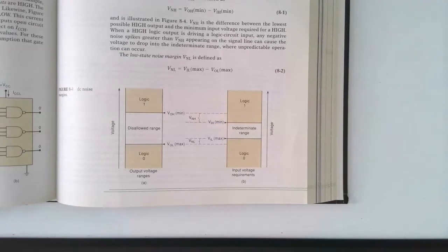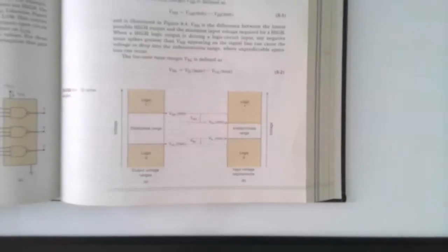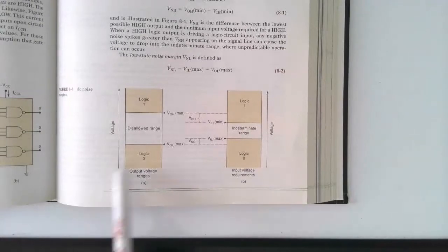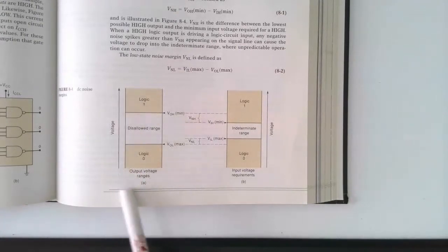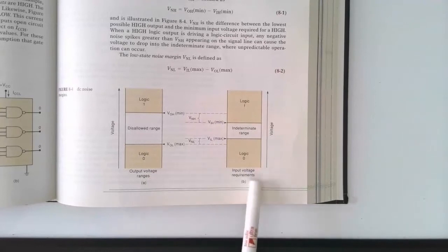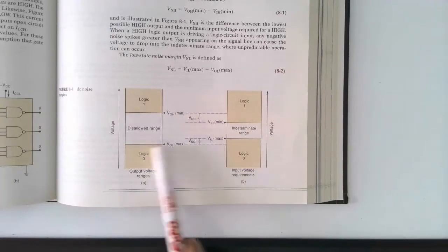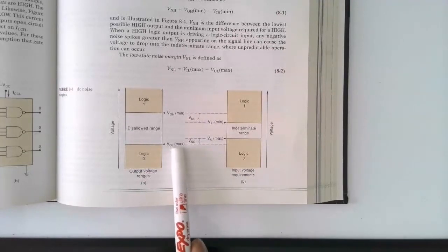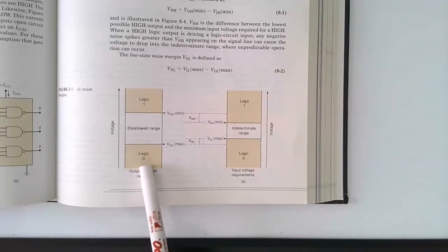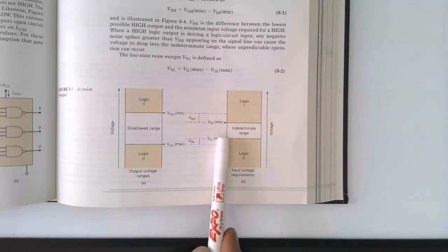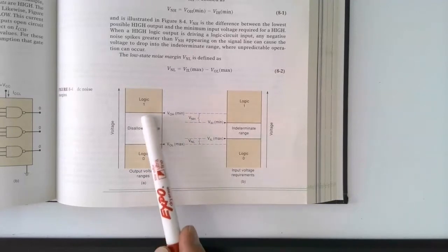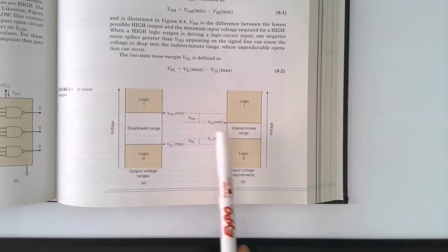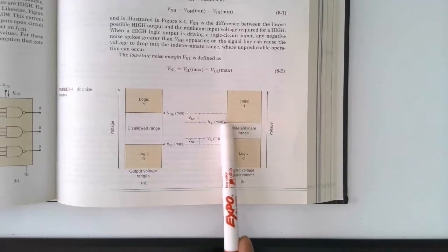Okay, and this is on page 493 in the book. I know I'm jumping around a little bit, but for some reason they broke these parts up in what I think is not the most logical arrangement. So what we're looking at here on the left are the output voltage ranges for TTL, and the input ranges. Now, they don't have exact values here because this is more of a generic picture. But the point is that our logic low output has to be less than the expected logic low input, and the logic high output has to be higher than the minimum high input.